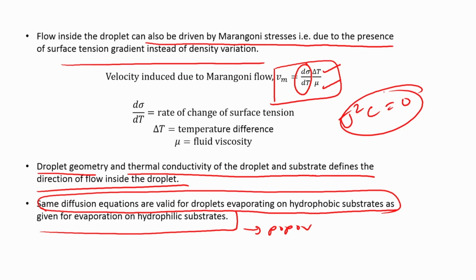So, the modes of evaporation become very important. The evaporation flux becomes highly anisotropic in nature, and that affects your particle transport, that blood example that we showed, your coffee stain and a variety of other things, which mainly happen due to this spatially inhomogeneous evaporation flux.